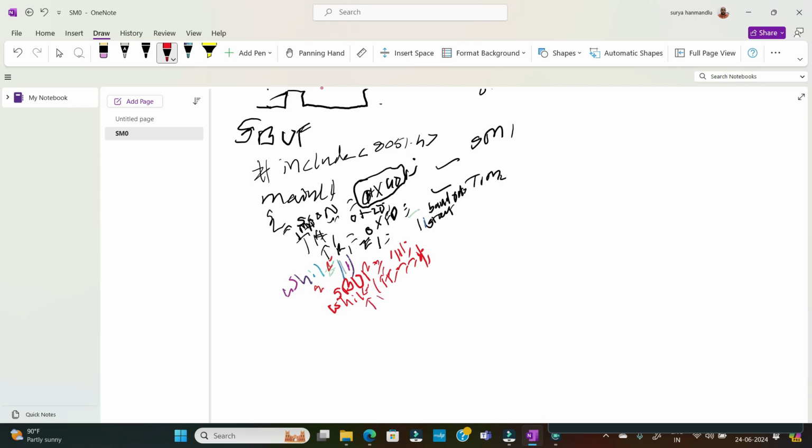Then immediately you have to clear TI. TI equal to 0. Okay. So this completes this while method, and this completes the entire main method. So this is a simple program to transmit a single character H. And the same steps hold good for the reception also. I will write that reception program here.